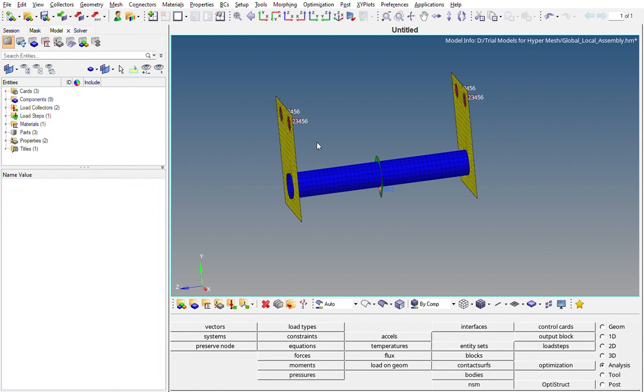So we have the mesh model, the material, the properties, the load collectors defining the boundary conditions, and the load step. So this is all, or should we do something more? We have to do some extra steps to extract the results. No doubt this will complete the analysis if we run it now, but we won't be able to get the output which we want.